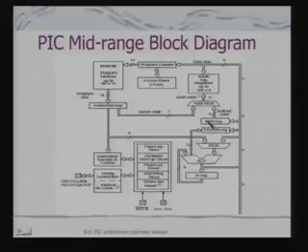We shall come to the exact mechanism used for indirect addressing when we discuss the instruction set of the processor. So at least from this architecture, what is straightforward is that I support immediate addressing, direct addressing, and indirect addressing, and primarily my operations use this RAM, which is nothing but the same register bank of a RISC processor.